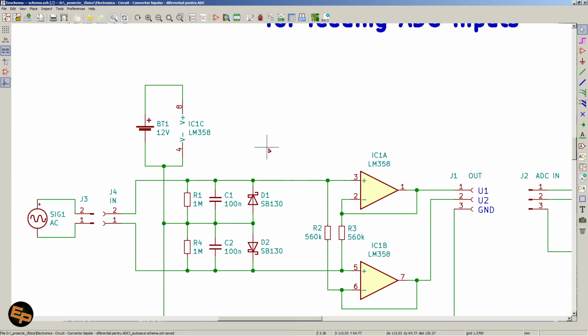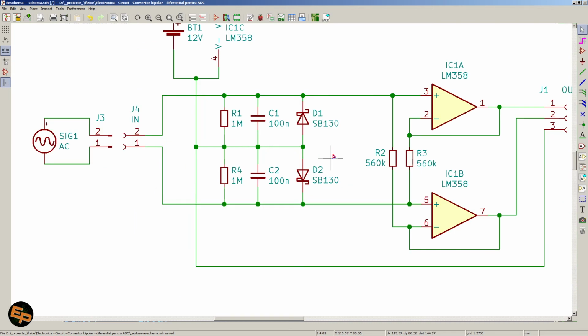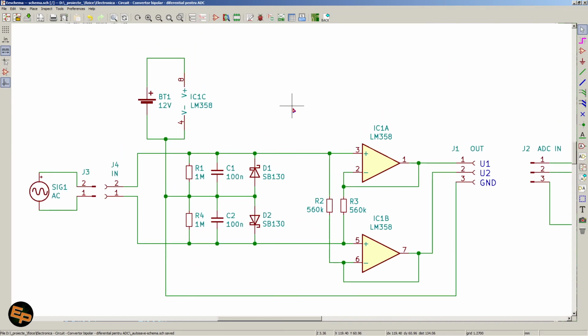And needless to say, we don't want that. So I've put these capacitors in order to basically reduce to the absolute minimum that annoying hum, that annoying electrical noise that gets induced, especially if we are working on a breadboard. Okay, that noise gets easily induced in the wires that we use on the breadboards, and it is overall annoying, not desired, and a problem that we want to eliminate. And essentially this is the entire circuit. Okay, it's not big rocket science.